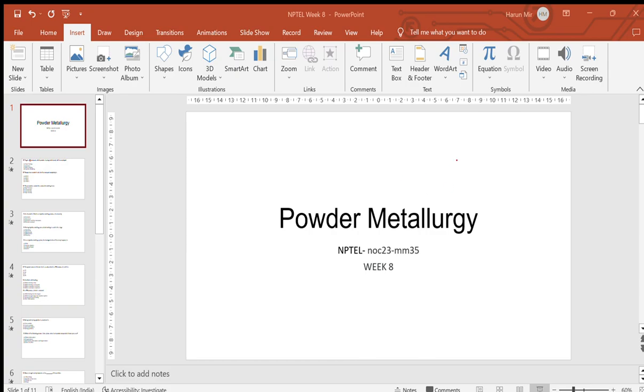So we can say that this is your powder content, how much powder you are adding, because that will affect your viscosity. And this is the critical solid loading. So for this critical solid loading, you need to tell what it is related to. Is it that the mixture density is low, or the mixture density is at its peak, or the mixture viscosity is minimum, or the mixture viscosity is maximum? At what conditions are you defining a critical solid loading?